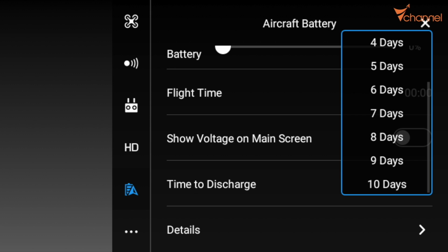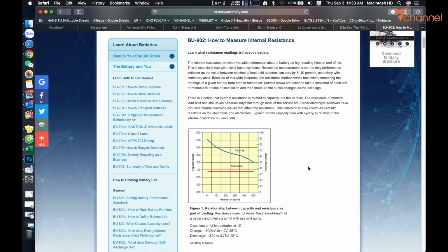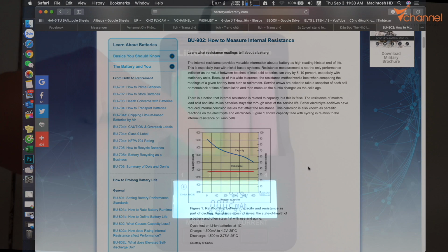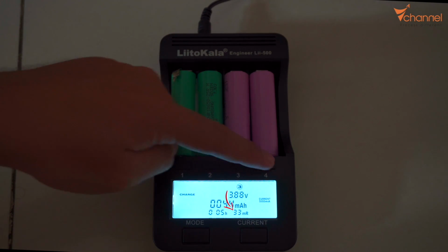But if it's a normal battery, we must discharge it manually. Next, the element to evaluate battery health is internal resistance. To calculate the internal resistance, you can use the formula. The new charger generation shows the internal resistance already, like this, right on the screen.